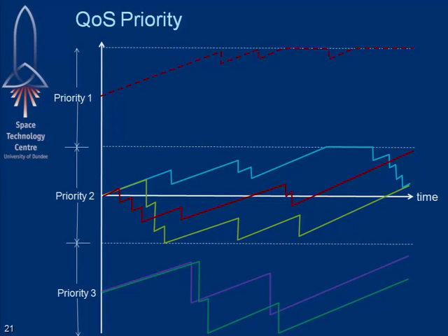Okay, so we have a mechanism whereby if one of these bandwidth reservation counters reaches its lower limit, it then effectively is no longer allowed to compete. So when you've used up all your credit, you can't actually stop a lower priority virtual channel from sending information, okay, because you've used up all your credit anyway.